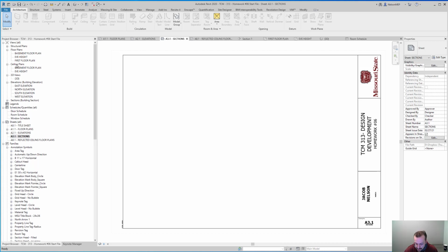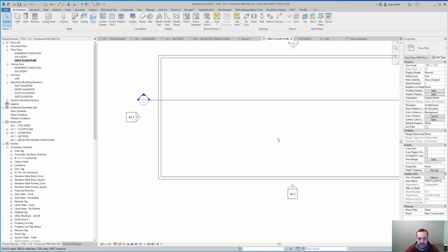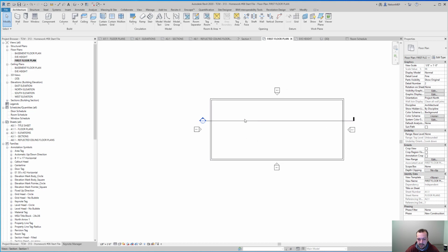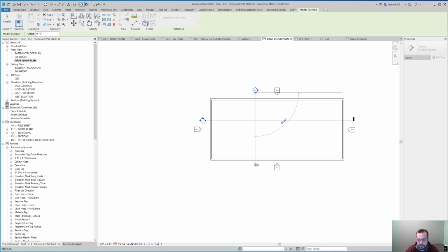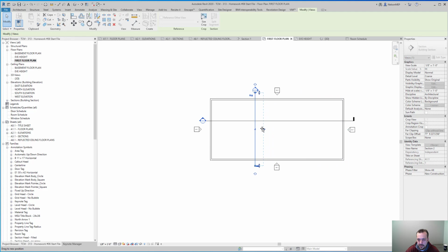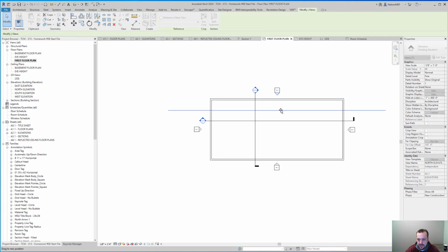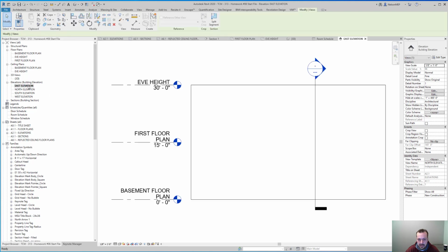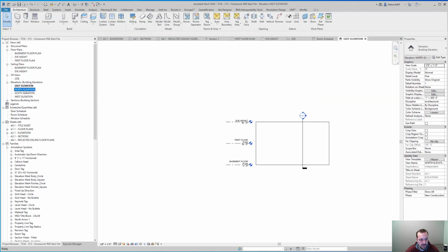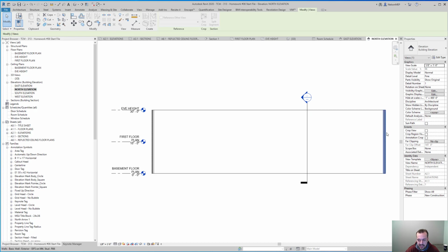So we need a north-south section and an east-west section. So if I go to my floor plan, to me we have an east-west section here. Now we just need a north-south section that's put in place like so. The other thing you want to pay attention to a little bit is the view of this elevation here. So that is my north elevation. I'm sorry, north. Okay, notice where that section goes.